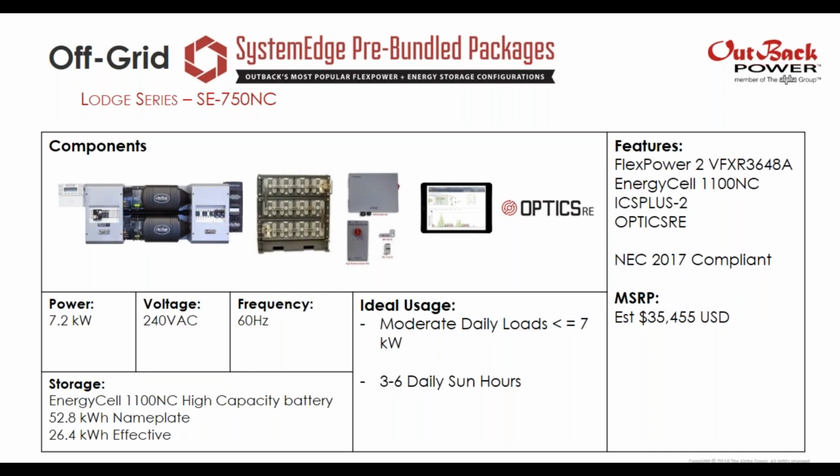So the nice thing with the nanocarbon batteries, if you're not familiar with them, is they're a lot less sensitive to partial state of discharge. So if you run them down a little bit and don't recharge them right away, they're not going to punish you as badly for that as a normal lead-acid battery will, because they've got a carbon nano coating on the plates themselves, and that prevents the sulfation buildup, which is basically what ultimately ends the life of most lead-acid batteries. So a little better cycle life and more flexibility out of those.